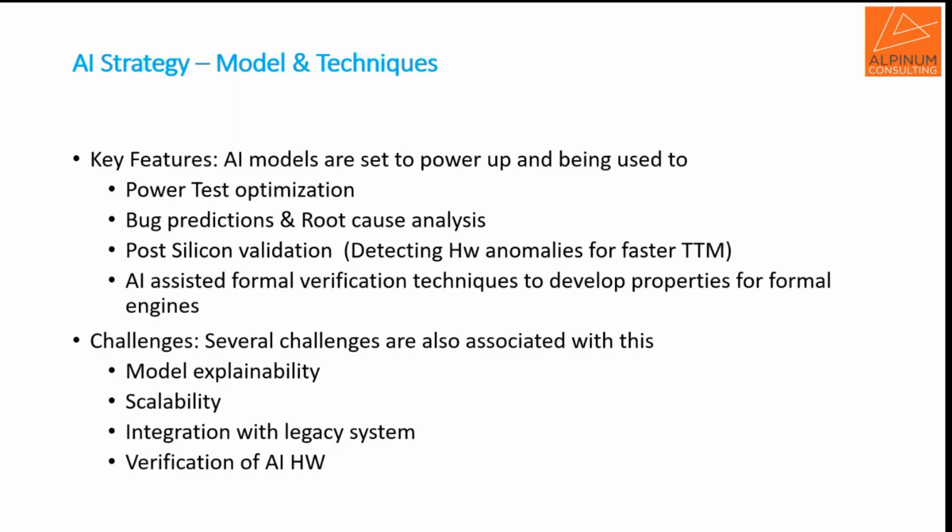So as a summary, the key features are that this is a powerful way of optimizing the tests in your design verification environment, and it can also help in prediction of the bugs, and can be extended for post-silicon validation and for formal verification and formal techniques.